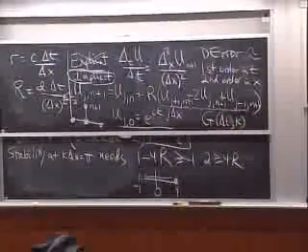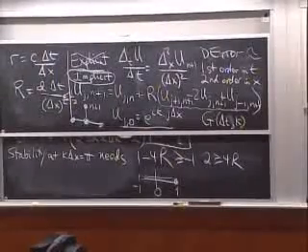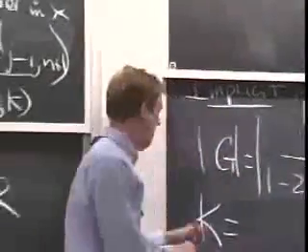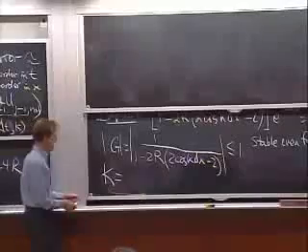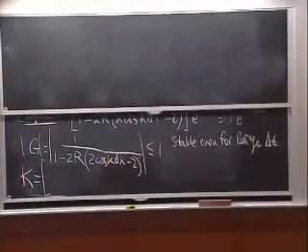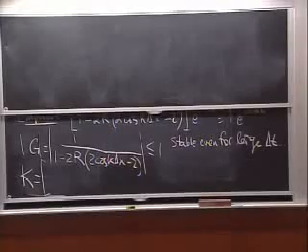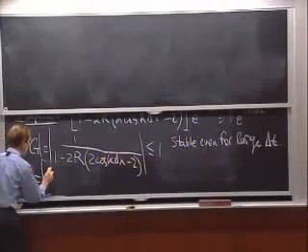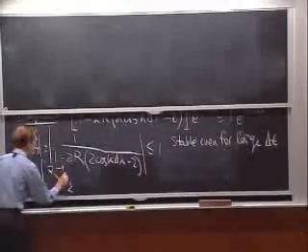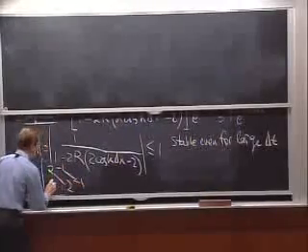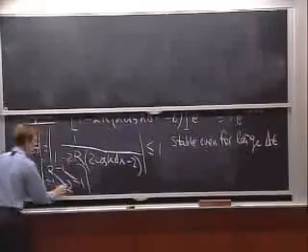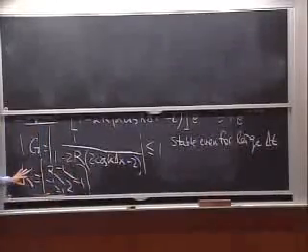So can I just remember the meaning of this matrix K? I'm going to stay with that letter because it's standard in finite elements for the stiffness matrix. So K, by definition, is the matrix with 2's on the diagonal, -1's above the diagonal, and -1's below the diagonal. And what size is it?